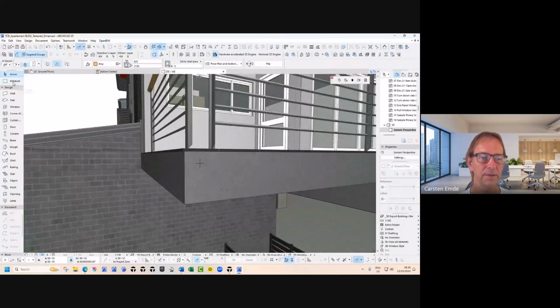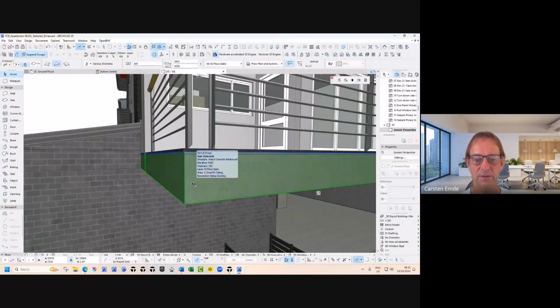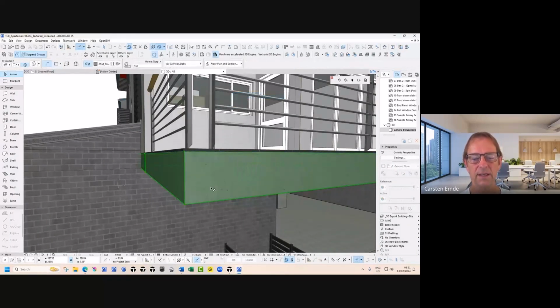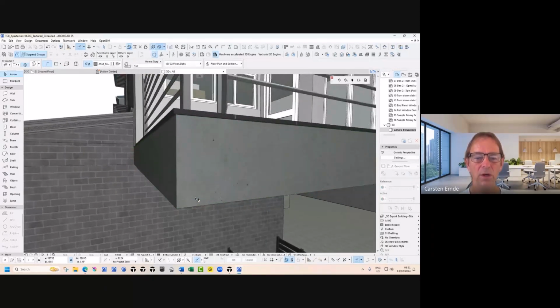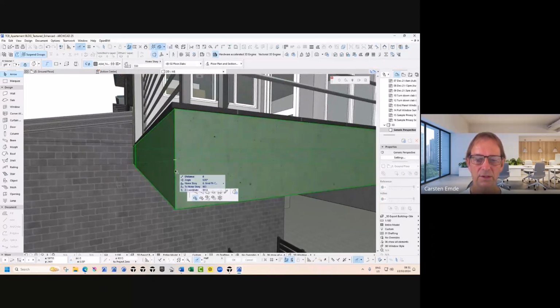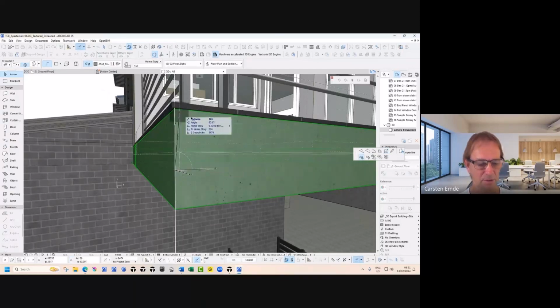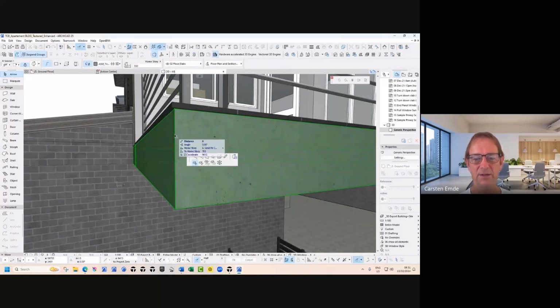So if I go here, let me select this one. Now I can't round those edges. That's just the way ArchiCAD works. So if I really wanted to, remember, this is just an example, say you have a close edge in your model. In ArchiCAD, I could convert this to a morph. Now it's not a slab anymore. And what I could do is give it a chamfer. I just do this, maybe apply to all edges. Let's see what it does. Whoops. Yeah, too big of a radius. There you go. Let's try again.